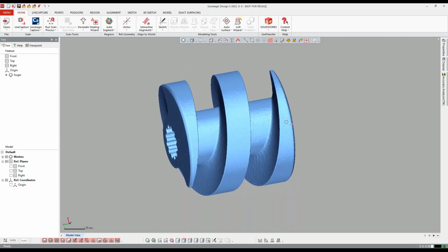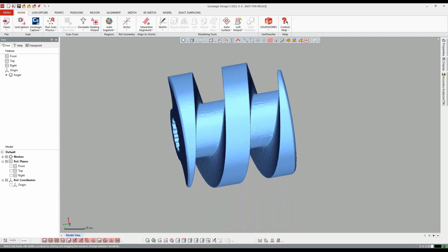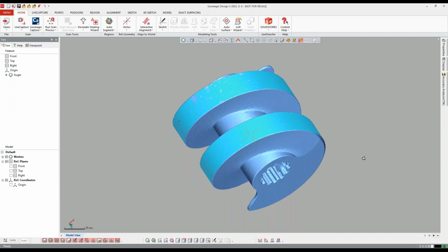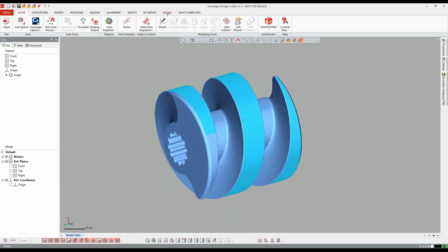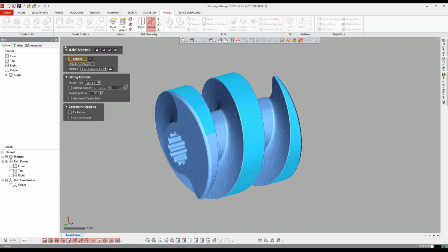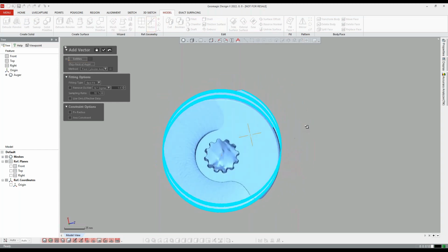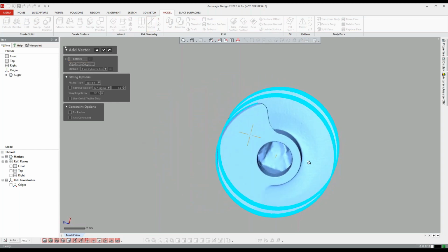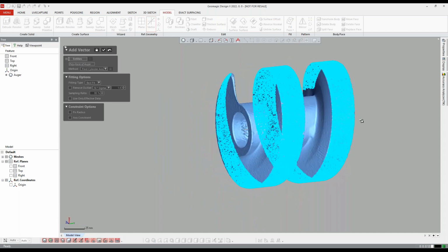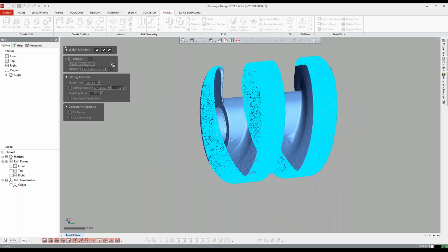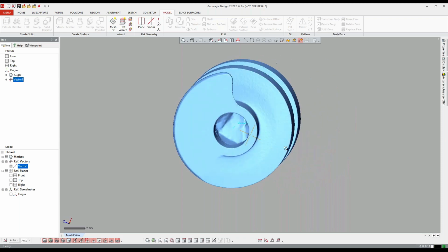I want to pull out the side inside the center. To do that, on most things I'll use our Smart Select tool to pull that out. So I can decide whether I think the outside is better for that cylinder or the inside is. Granted, everything's right on the Home tab here if you want to use that. I like going in the model and just hitting Vector and Find Cylinder Axis, and I can plug that in and pull that out. Again, we're going to want an accurate cylinder axis for whatever the revolve is, whether it's the inside or the outside, depending on what you pick.